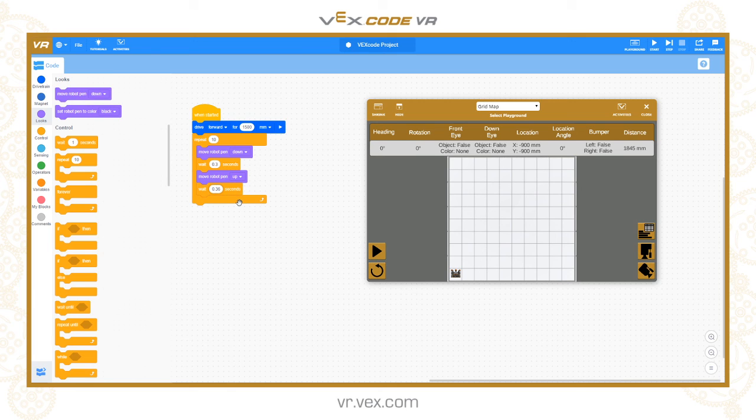So as the robot is driving along, the pen is going down, up, down, up, down, up. But when I'm in blocking mode, let's see that code in action. I run it, and at the moment the code is blocking on this line here, so it's just driving along until it reaches 1500. And now the pen is going up and down, which is not much use because the robot's not moving anymore.